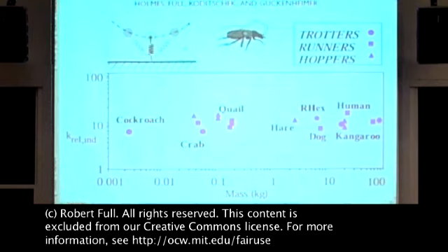You can see that they're all pretty similar, right? This is a huge spectrum of masses. And yet in the framework of the slip model's spring constant, they all behave pretty similarly, humans, all these things. So if you look at these systems through this simple model, they not only look similar to one another, but their dynamics and their center mass direction, everything like that, are pretty well described by that kind of behavior.